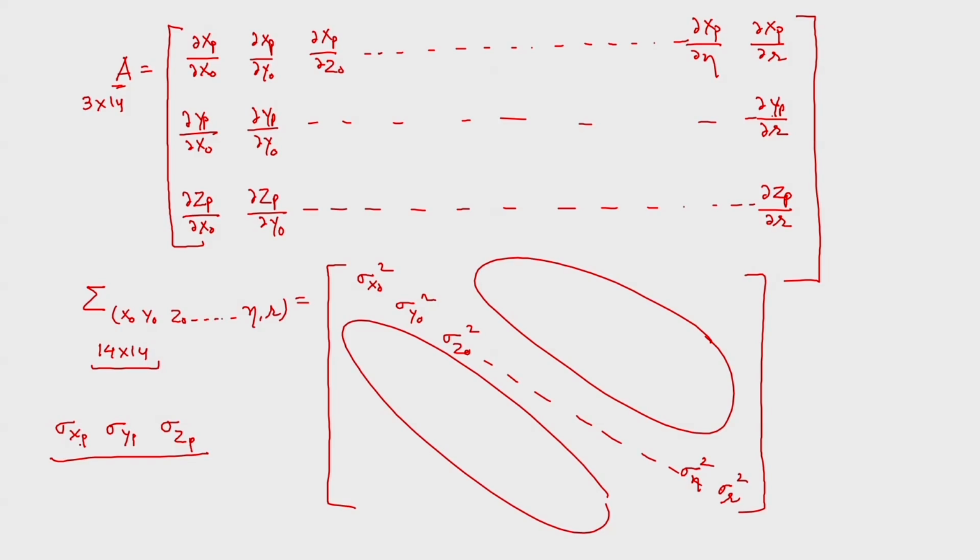What about the values of these variables? So, I am going to share typical values. GPS trajectory coordinates generally have 5 centimeter errors because sigma h0 is given as 2 centimeter plus 1 ppm, and we have the baseline equal to maximum 30 kilometers.